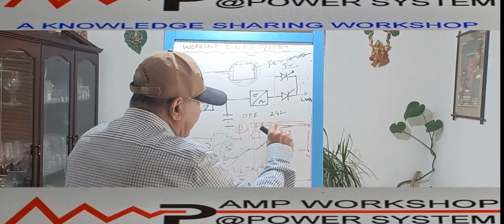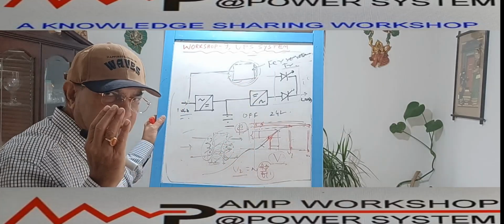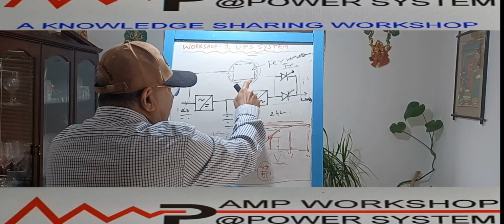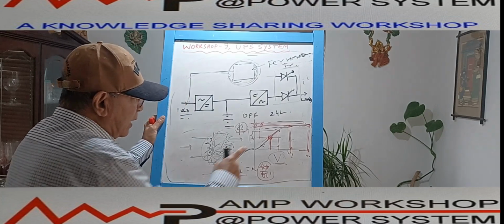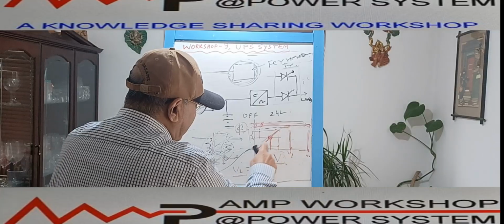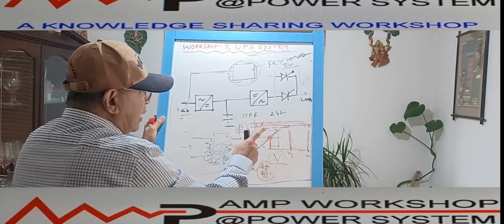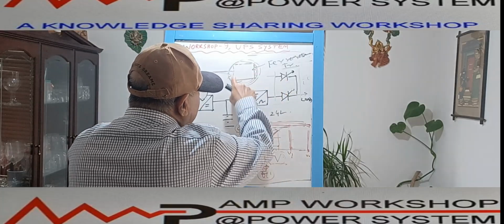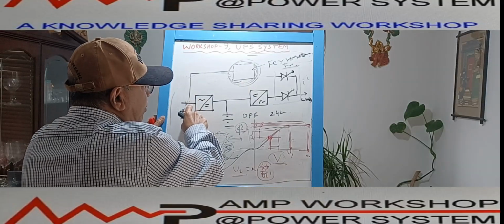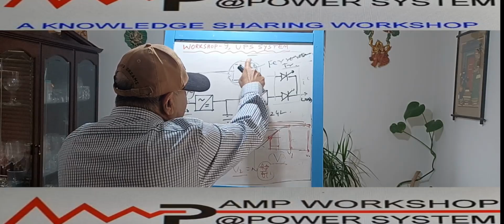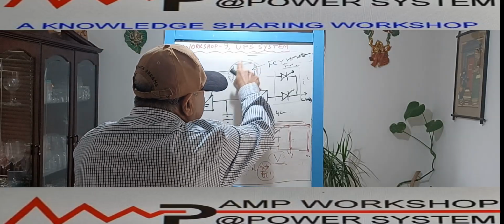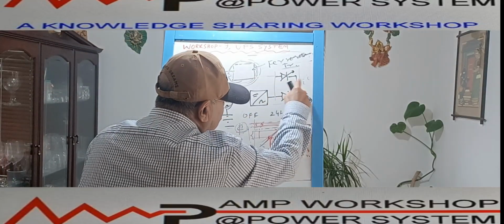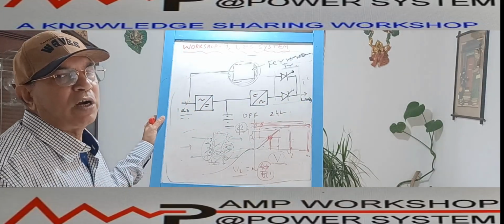Second point, as the magnetic core is always saturated, the moment the power supply fails, there will still be output voltage, because this flux density will not suddenly come to zero; it will take some time. So during that time is the transfer time. By that time, though the main supply is not available, the ferroresonance transformer, due to the stored magnetic energy, will release that magnetic energy as electrical energy through the static switch to the load. So interruption will not be there.